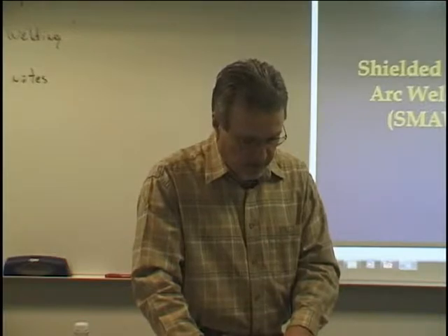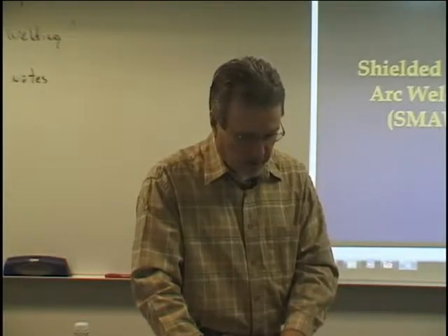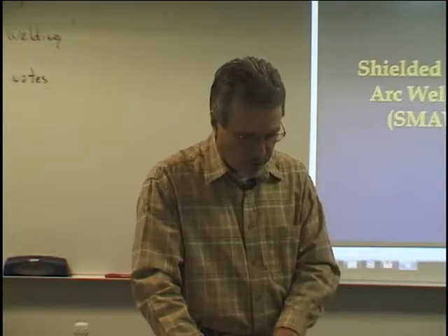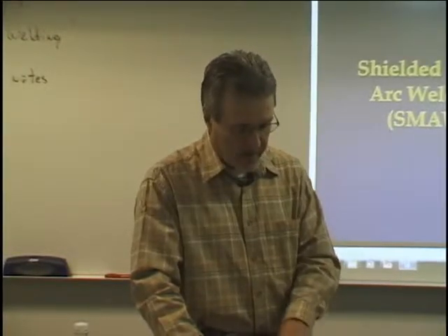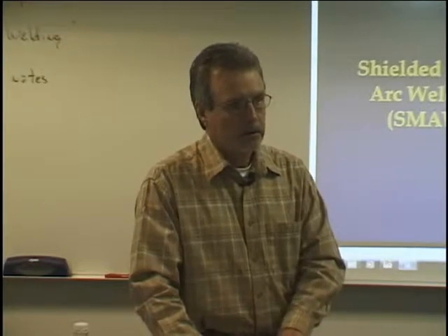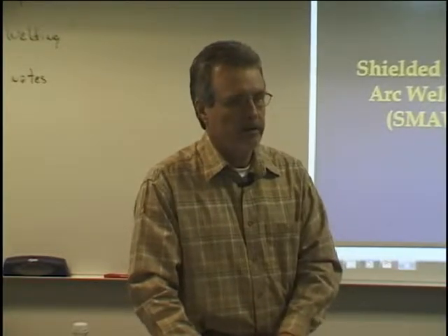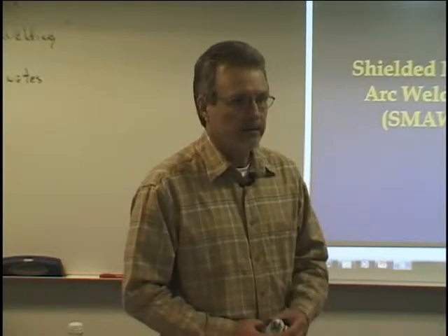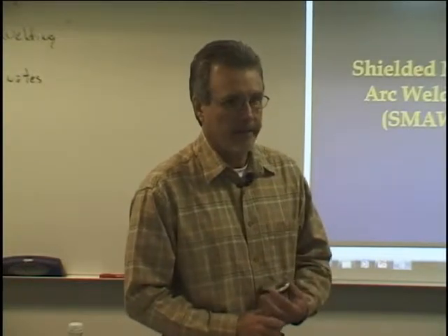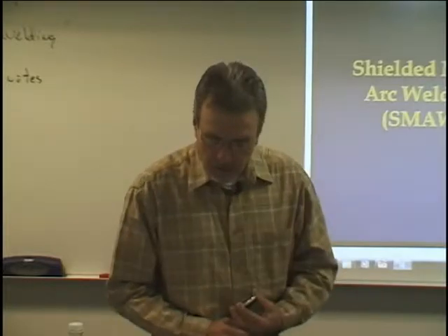Continuing, it says, any filler metal used has either a melting point approximately the same as the metals being joined, or a melting point that is below these metals but above 800 degrees Fahrenheit. So they put that figure in there for a reason. You're going to want to remember 800 degrees Fahrenheit. You're not doing welding if you're below 800 degrees Fahrenheit. Okay? Let's go over to the next page.